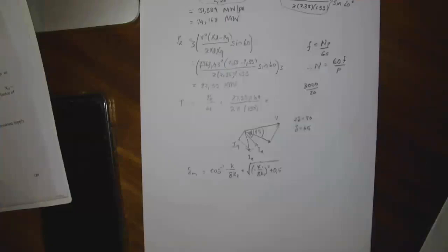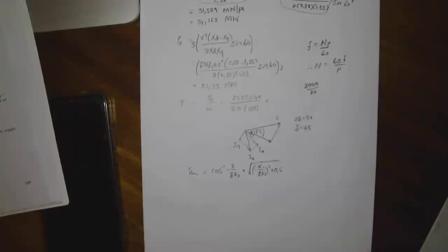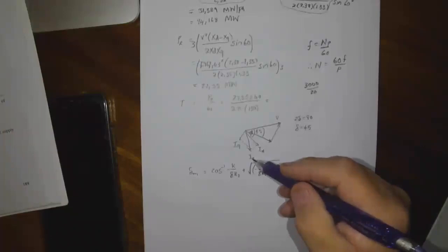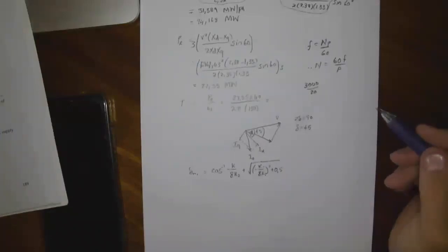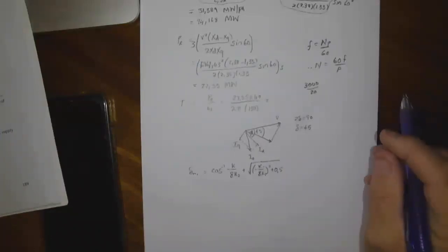Another question, sir. Let's say, for example, on the question when excitation is switched off, but you've also given me R. When I calculate my new developed power, do I also add the 3I squared R along with the rotational losses? Yes. Because you still have the current flowing, and therefore it will be I squared R.